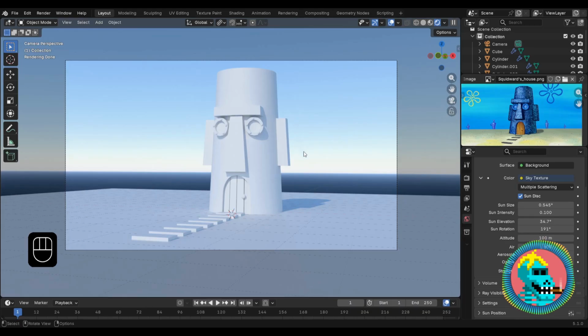This is the result we got. So, we set up the global illumination. Also, to make the shadow smoother and less harsh, we can change the sun size. By increasing the size of the sun, we make the shadow smoother.